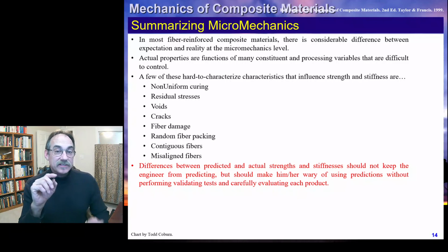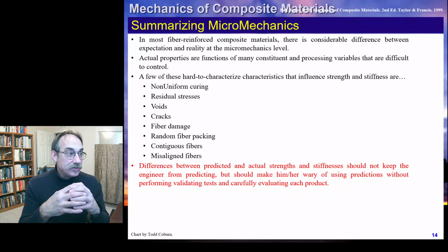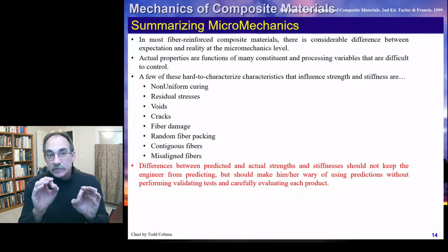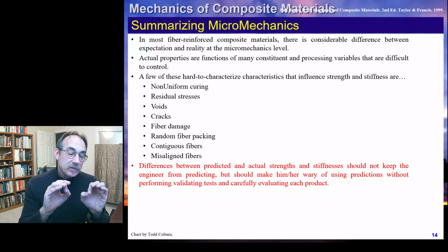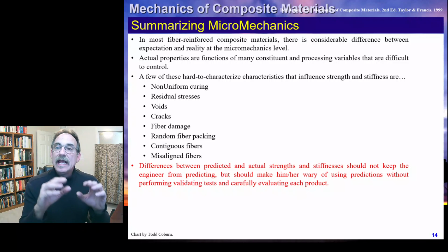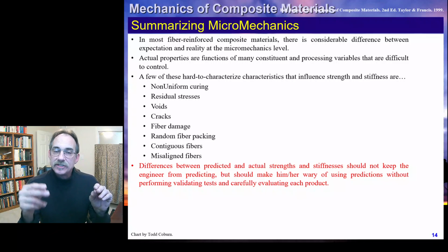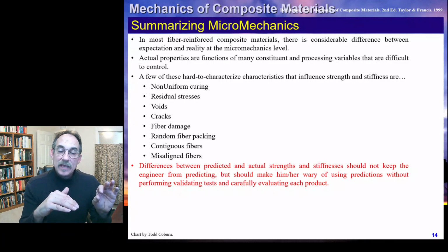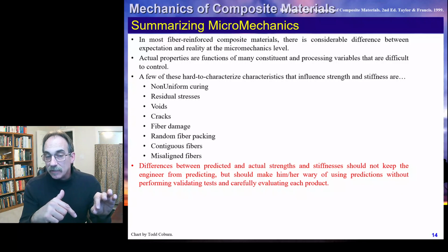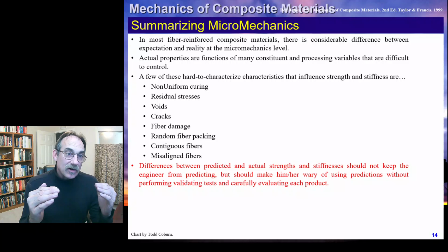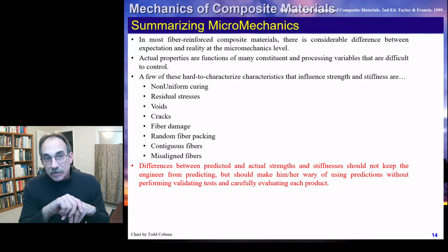We have to be careful, because composites, because of all the variances, can involve extensive, exorbitant amounts of testing. However, a good engineer with good judgment and understanding of those composites can often break that down to: we can do this direction, this direction, this direction. With these kinds of configurations, we're going to predict up front, see how that behaves, and maybe try it in this application to make sure it played out the same way as we predicted at the component level, and can cut costs by using good engineering judgment.